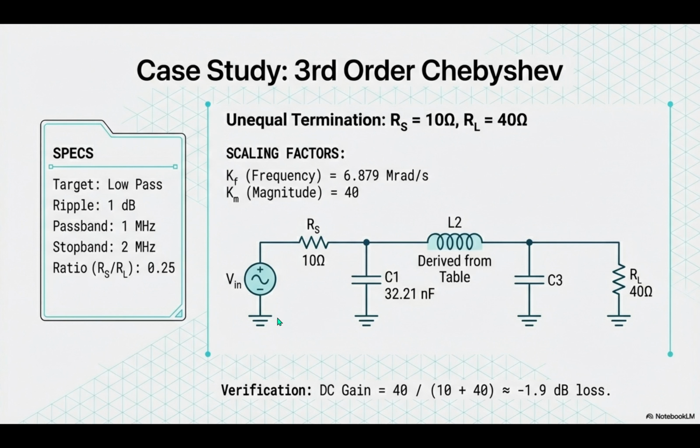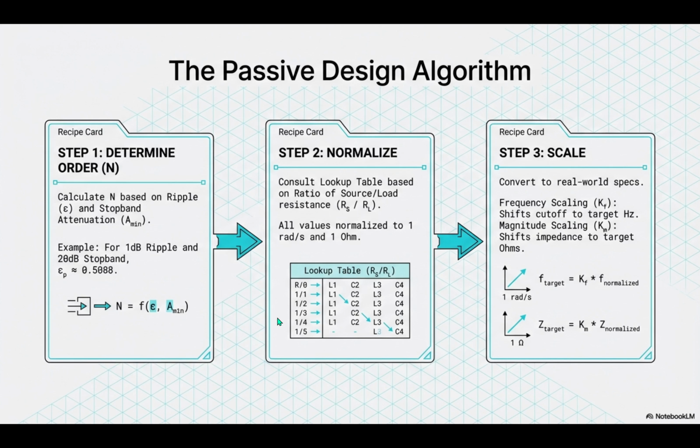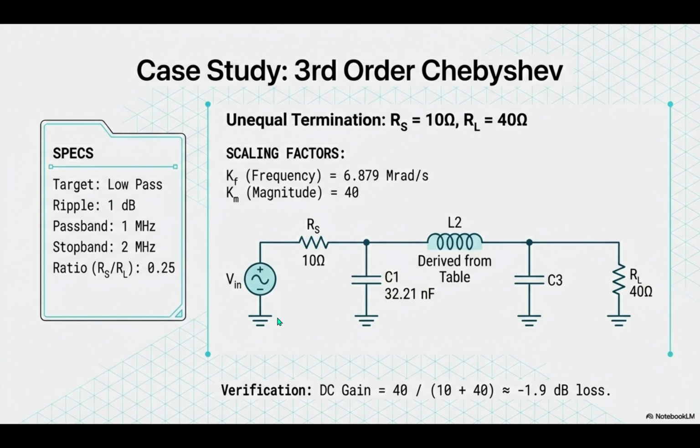Okay, imagine a table. A Butterworth response is a perfectly flat tabletop. A Chebyshev tabletop is warped. It has waves in it. In the passband, the frequencies you actually want to hear, the volume isn't perfectly consistent. It wobbles up and down a little bit. So you're accepting a little bit of distortion. Some frequencies are a bit louder, some a bit quieter, in exchange for that rapid descent into silence for the noise. Precisely. You sacrifice linearity for selectivity.